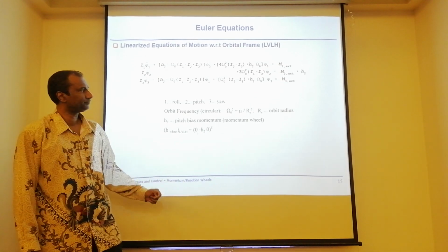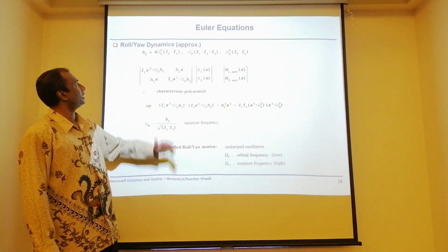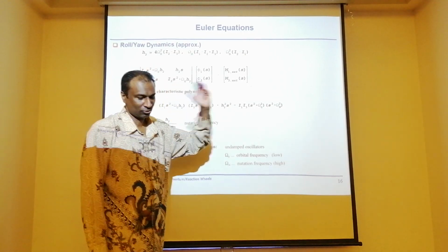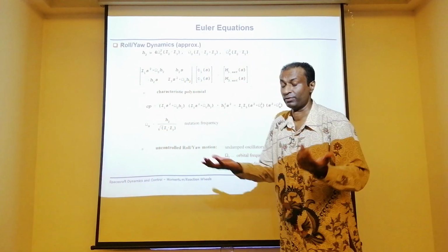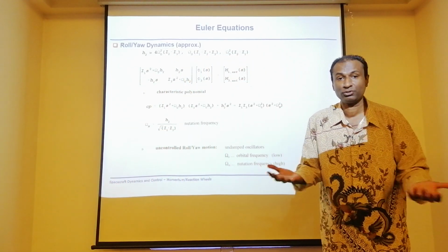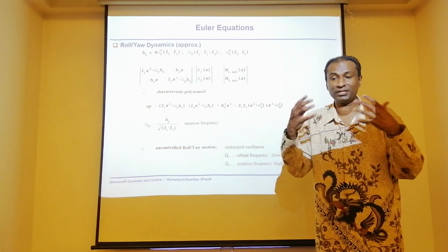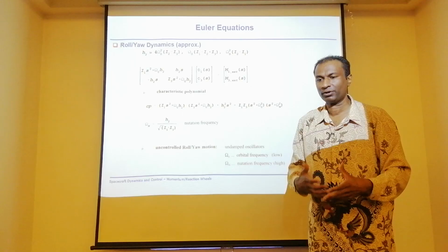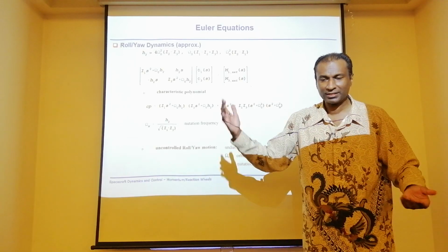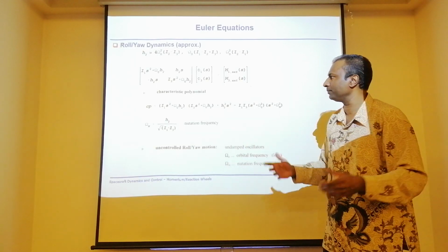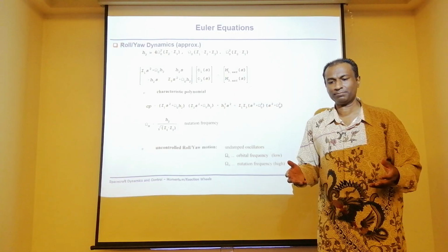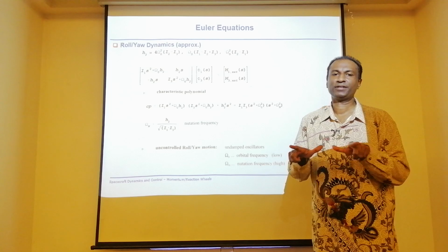Okay, go on. Alright, simple again, same thing I've treated, roll yaw. Let's see the roll yaw. We don't have to worry much about the pitch, because in pitch you have active control. How much of disturbance you give, no problem, because we have a momentum wheel. The momentum wheel can give out the torque instantaneously. You can start accelerating and give torque, no problem. Let us worry slightly a bit on the roll and yaw, because it's only passively stabilized by the stiffness.